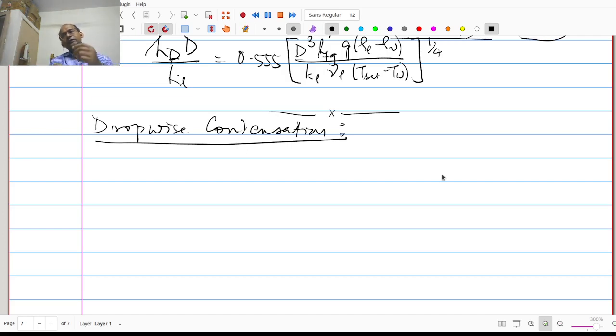So wherever the surface has natural faults of some kind, some cracks or some pits or some imperfections of the surface, that is where the nucleation sites are. So when the plate is cooled, the vapor comes and starts condensing in the small cavities and pits, and then it starts growing into a droplet.